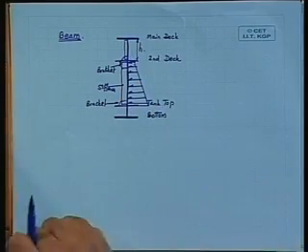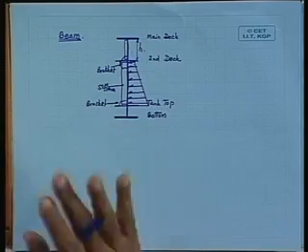You may ask me that I have not shown any in-plane loading here. Two things. When we are considering the flooded condition of the bulkhead, then the stresses generated due to the transverse load are much larger than whatever is imposed due to the in-plane stresses.